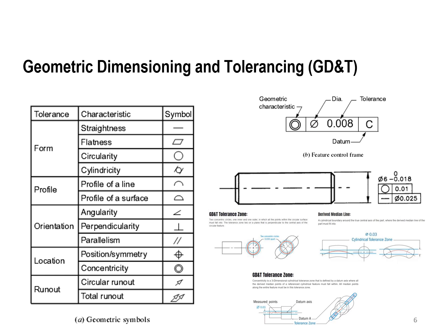If I would like to have the features for the control frame, I can have the square, which is going to have the geometric characteristics, which can be, as we mentioned once again, the concentricity, or I can have the circle with the cross in the middle. I can put the phi, which means diameter, and the tolerance of that diameter, and the C is going to be the datum center. Again, I can use that as follows. It's going to be the circularity, with a tolerance of 0.01, and the diameter is going to have the tolerance of 0.025.